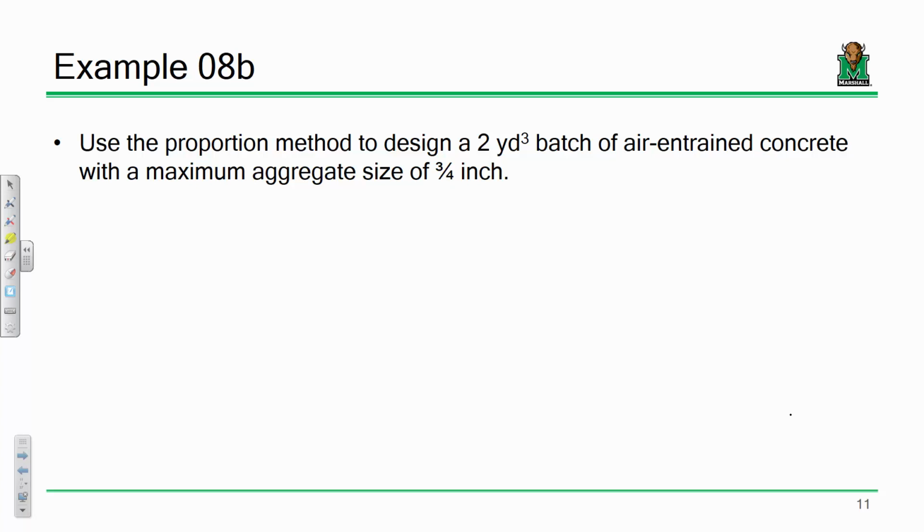The only other thing I would add, and that we're really not talking about, is waste factors. This is a really simple concept, but it is worth mentioning. If you've got a given project and you need to place 10 yards of concrete, do you order 10 yards of concrete? No. You order a little bit more to account for spillage, and it's called waste factors. So if you wanted to apply, let's say, a 10% waste factor, and you needed 10 cubic yards, order 11 cubic yards. Order a little bit more. Everybody okay with that? Just something to keep in mind.